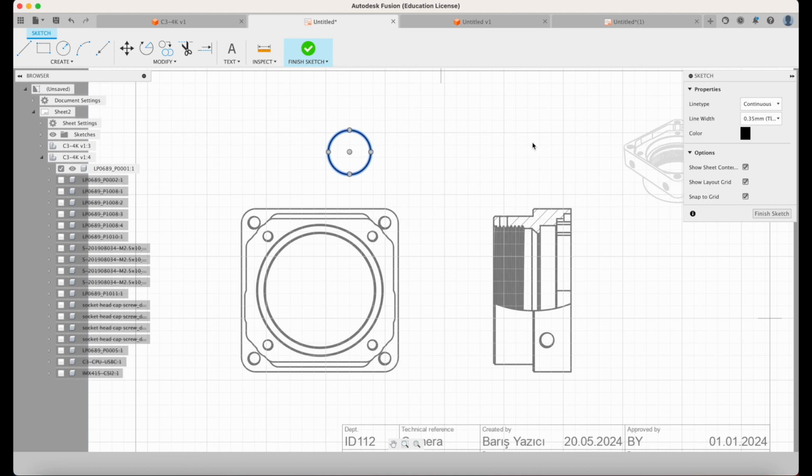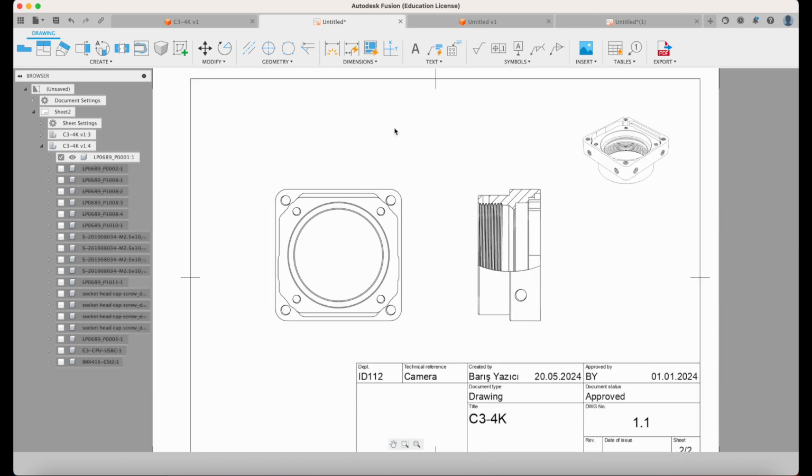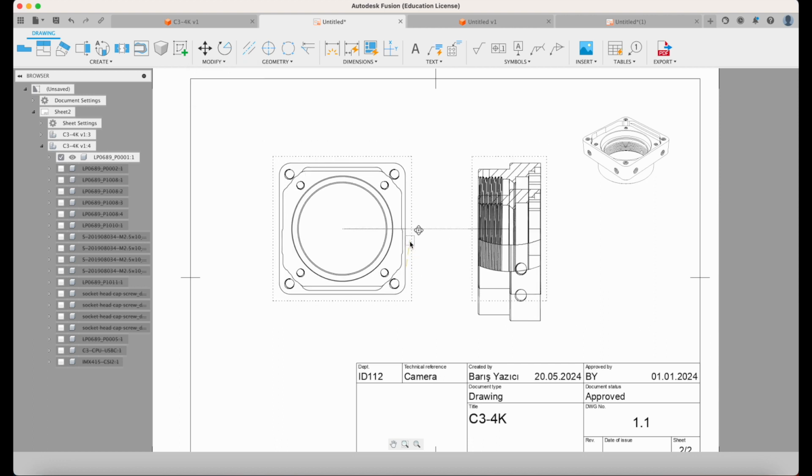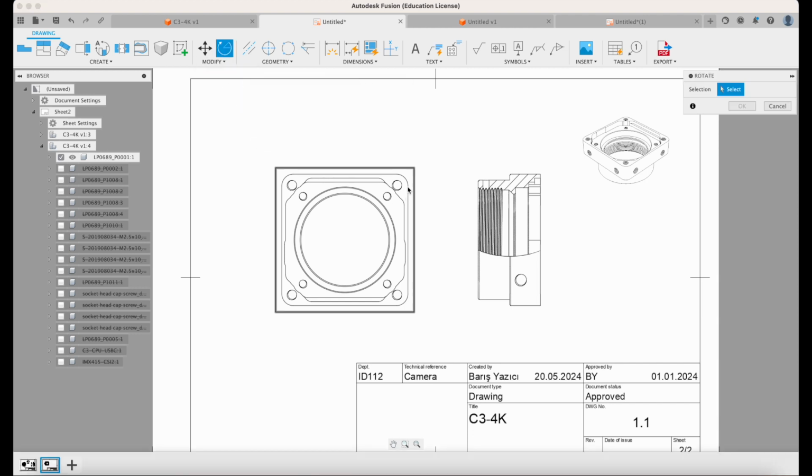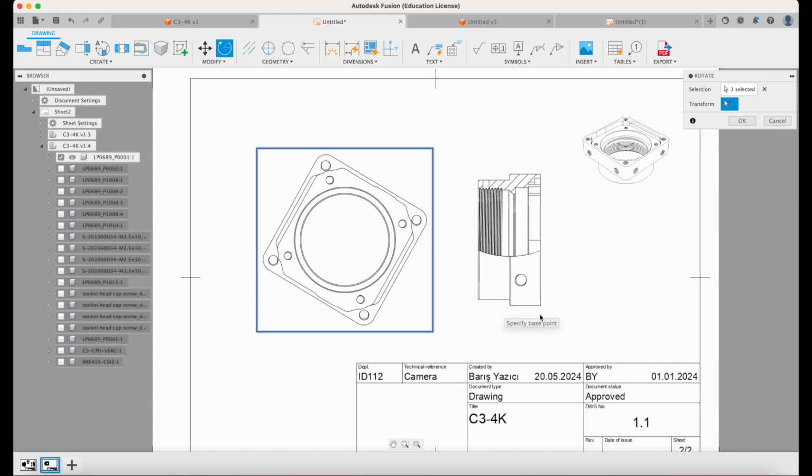For this example, I don't want to create anything that is marked on the drawing because we're going to get into dimensioning now. Now, the modified tools are the things we talked about. We can use move, and sometimes you might need to use rotate, okay? And it will allow you to rotate items based on a pivot that you select, okay?